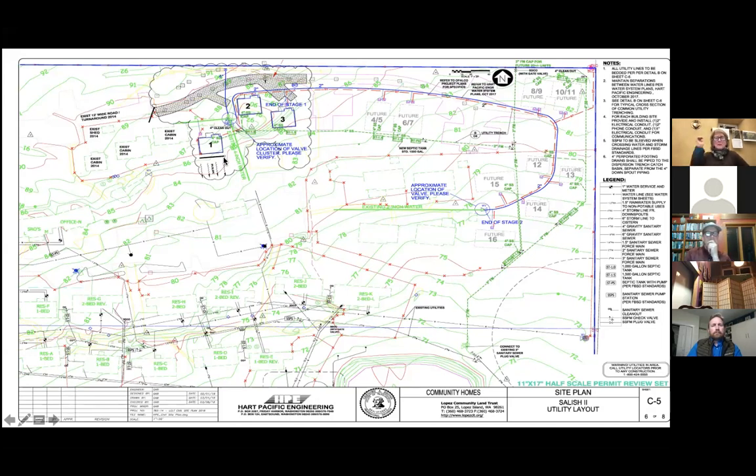And that's one thing you'll notice more about stormwater now: you really want to avoid concentrating, especially fast moving water, in small ditches, culverts, etc. They prefer dispersion trenches, which are gravel trenches, or a level spreader, which is actually a concrete piece formed with little V's in it to let the water wash over it naturally.